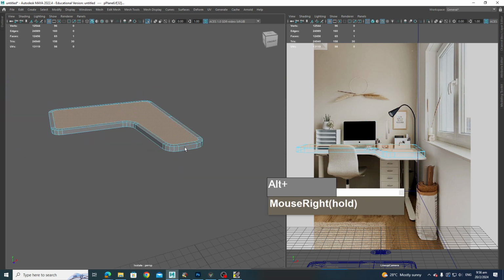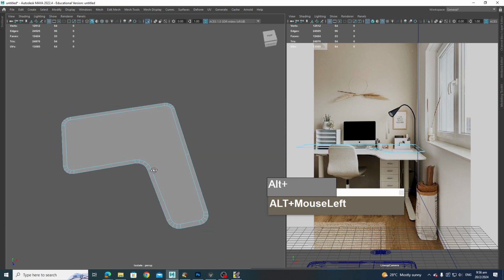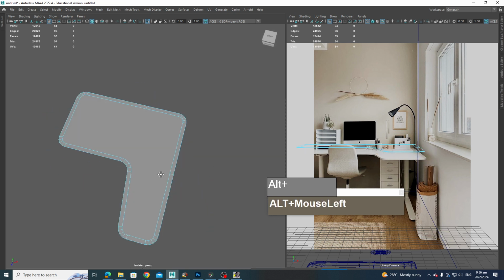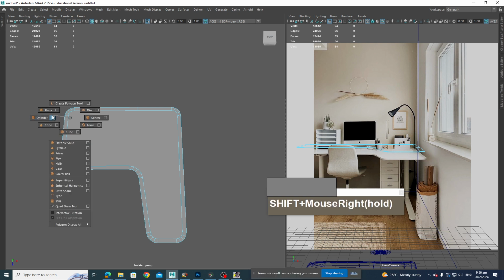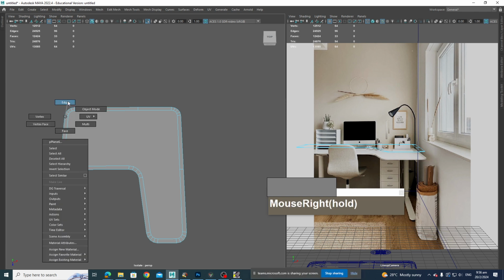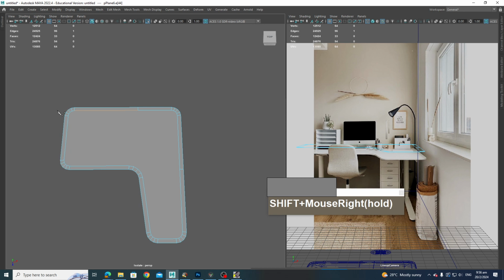Now the bottom edge face, we don't need this anymore. We can delete them away. So we end up with this flat face looking like that. And then using the same technique as what we did earlier on, we will just use the multi-cut tool.